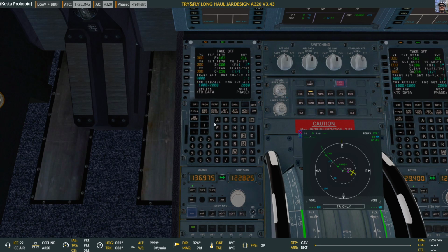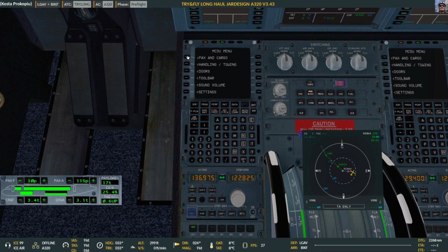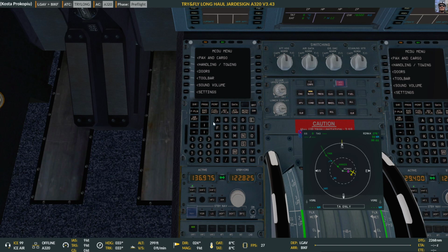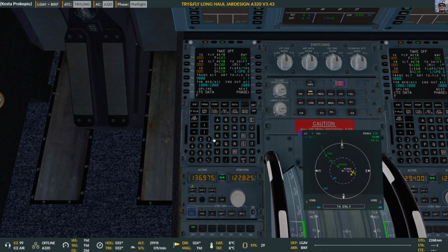Let's go to the performance. Transition altitude is 9,000. The flaps settings. Oh, I did not check. Let me quickly get the Bucks cargo again. So 0.6 up with probably flaps 1. So 1/0.6 up. The flex temperature, F45.